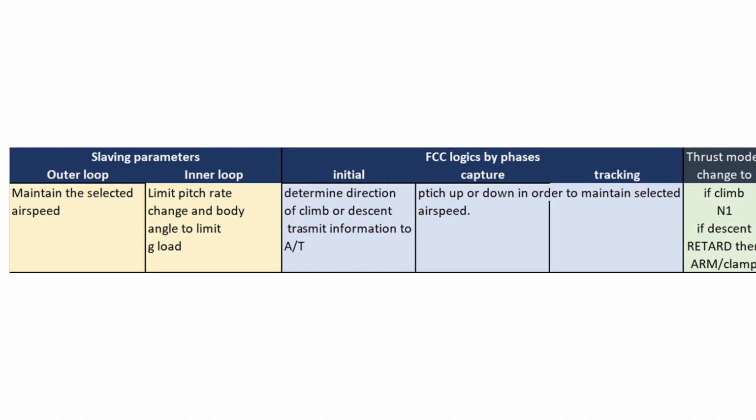Flight level change, climb and descent, open climb and open descent modes. Well, we have seen the vertical speed and the flight path angle, which are modes that use constant angle. Well, now the angle only depends on the thrust setting. Let's therefore take a look at what this leveling parameter is on the open climb, open descent.